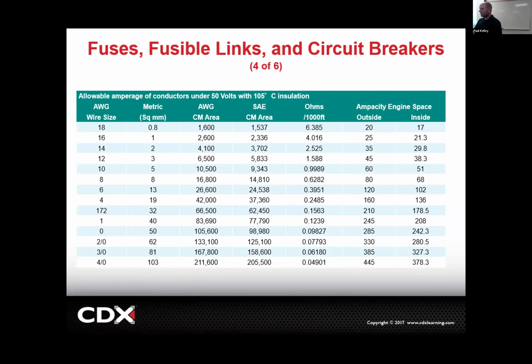So if you added enough lights that you need to pull more than 20 amps, you can't simply throw a bigger fuse in. How could you draw 25 amps with those lights? Look down. This can do a maximum of 20. If you want 25, you'd have to use this wire size, a 16. Doesn't that sound smaller? You had an 18. It's the other way. If it's 18 gauge, 16 is bigger, 14 is bigger, 12 is bigger.